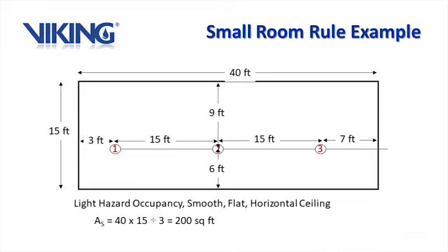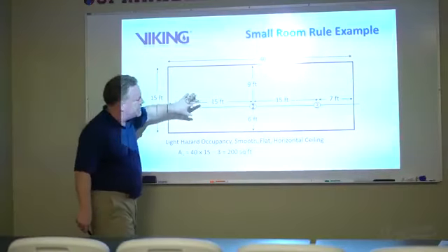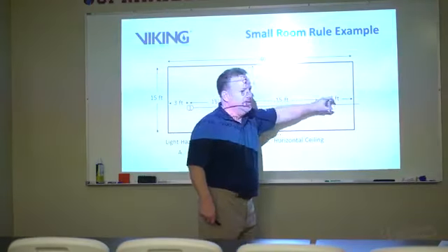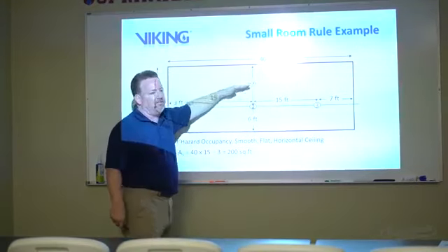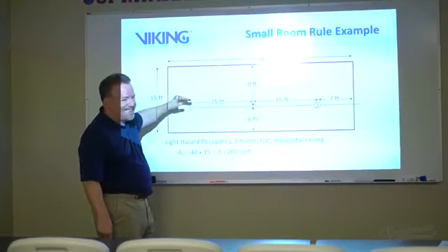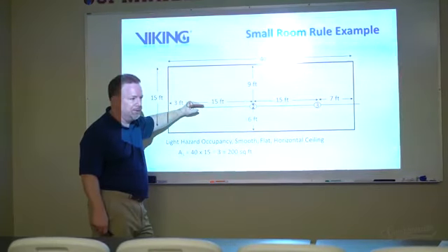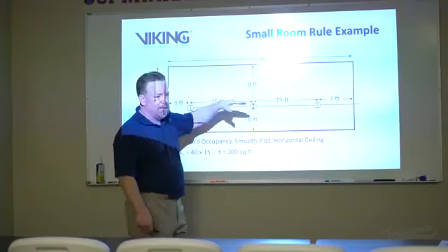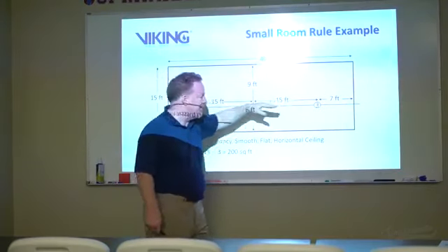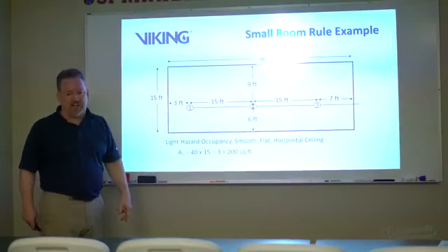Is that permitted? Yep. By virtue of the area of operation, I can go up to 225. So each sprinkler is covering that. Now, because I may have, I don't know, something up above the ceiling line, I can't get the sprinkler system to the center of the room. Okay, maybe I've got ductwork, maybe I've got something going on that I can't get up there. I have to push that sprinkler line off to the side.